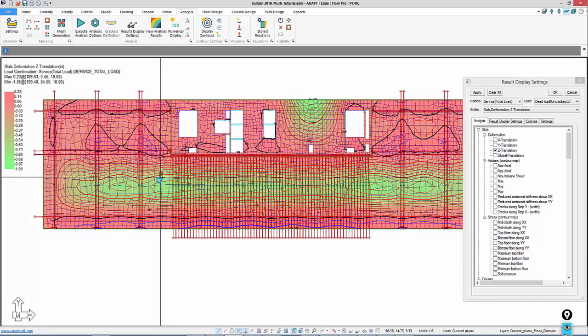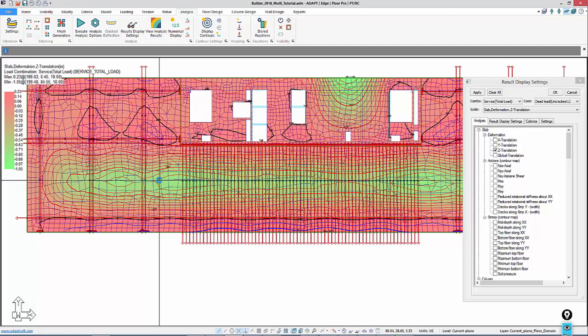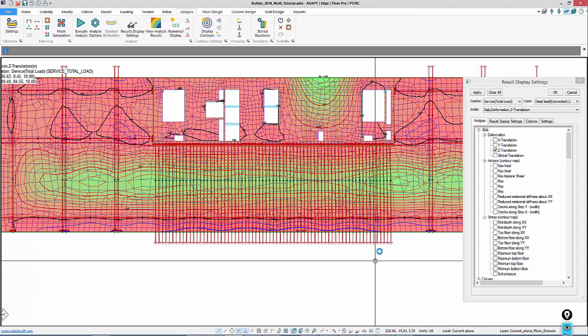So assuming that our multiplier is, let's say, 3, we have a total long-term cracked deflection of 1.8 inches, maybe plus minus. If we then evaluate that against our criteria for total deflection or for live load deflection or whatever the deflection evaluation is, we can determine whether or not we might need more PT initially. So those are just some things we can do with the initial analysis results that are produced once we run the analysis.